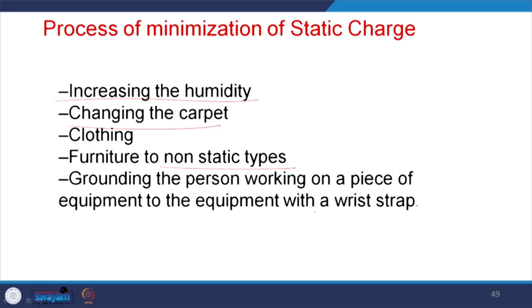Mostly it is used when technicians are soldering MOSFETs, because their hand may contain a sufficient amount of charge if you rub it, and once you touch with the hand, this charge will be trapped between the gate and source of the MOSFET, and thus it will automatically turn on. So, ultimately you get a MOSFET in a short circuit condition. For this reason, when they are soldering, they wear the wristband.